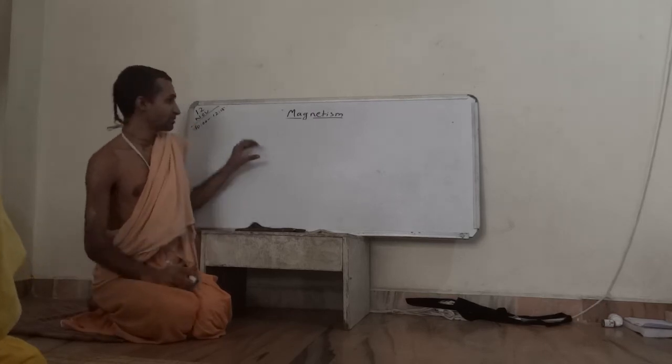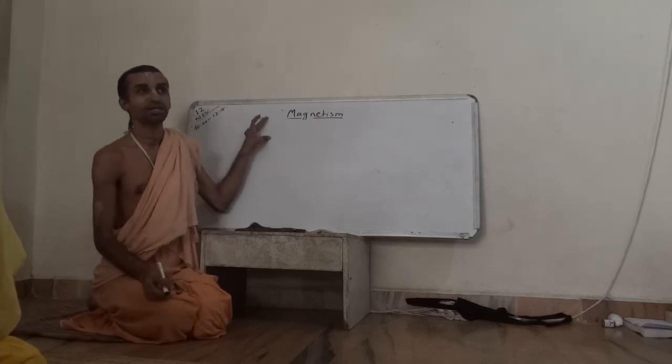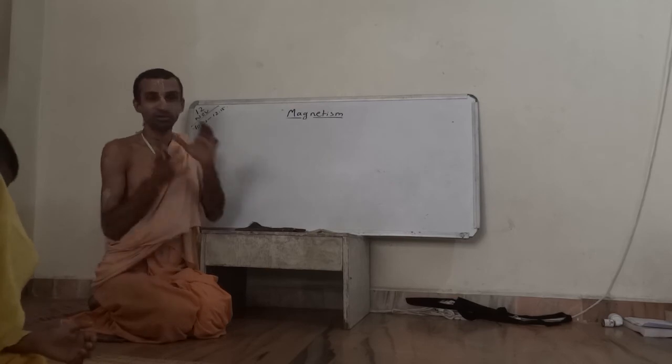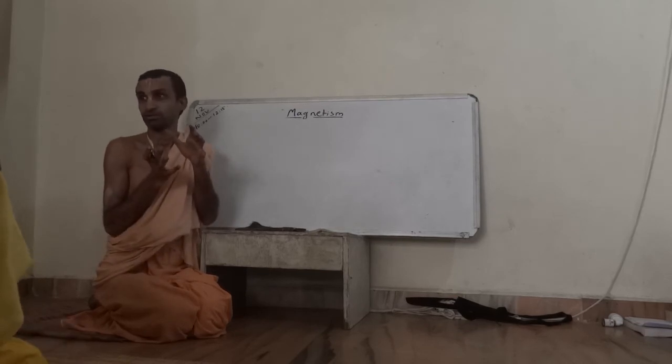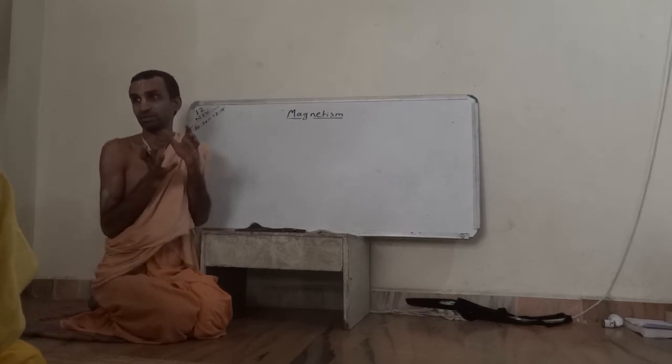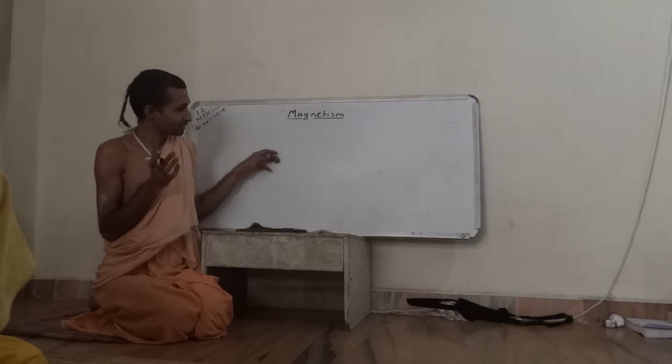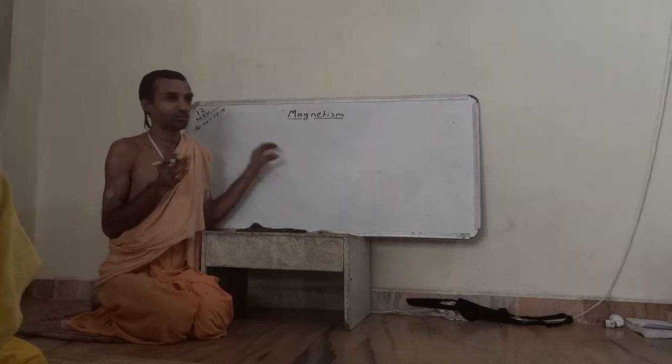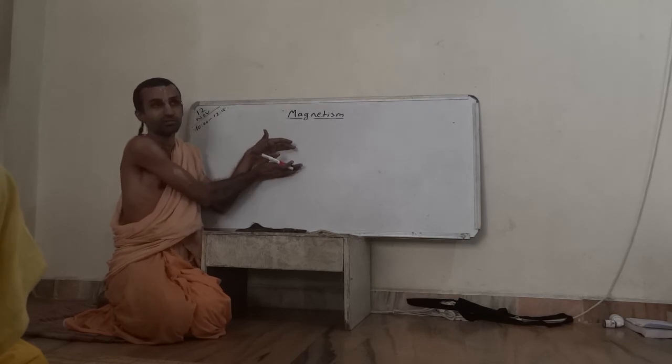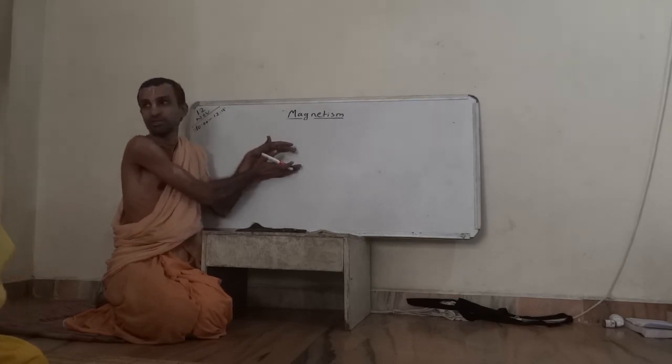It depends, because when the steam is at high pressure and high temperature, the volume of the steam, the space it covers, is lesser because it is high pressure. When it produces motion, at that time it requires less volume. So the turbine required for that will be of lesser size.